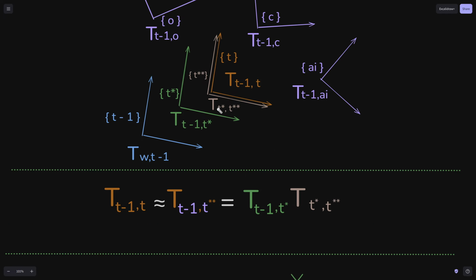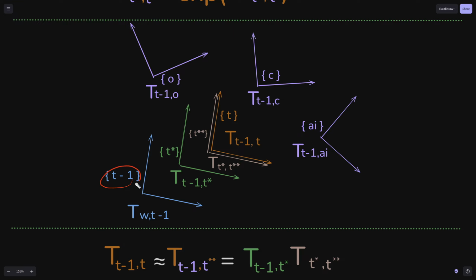Also, bear in mind that sometimes you will not have the t minus 1, right? So you will have 3 poses, and you need to average them out. So if you don't have t minus 1 and you have those 3, what do you do? One thing you can do to average them out is say, average the translations, do the logarithm of the rotations, average them out, create a transformation of those, and this is a good initial seed. Okay, a good initial seed.